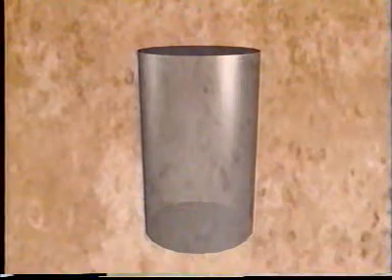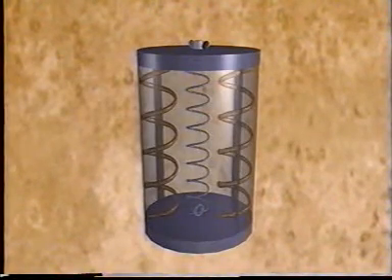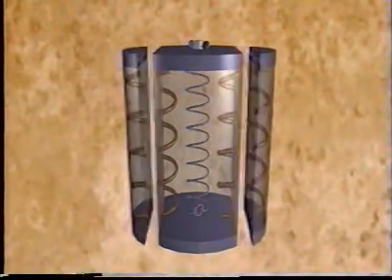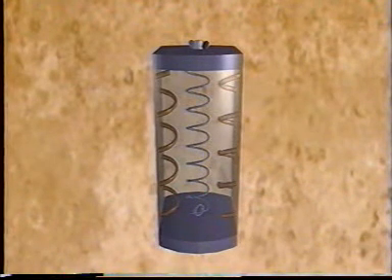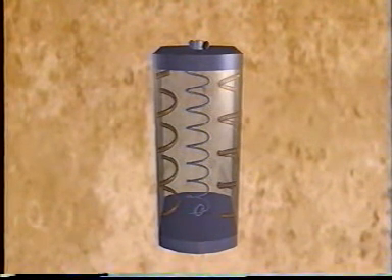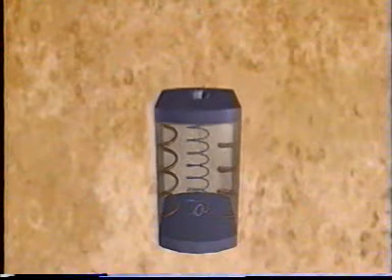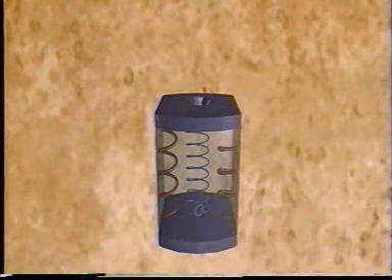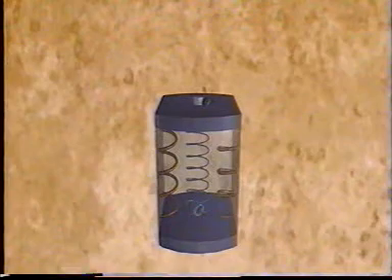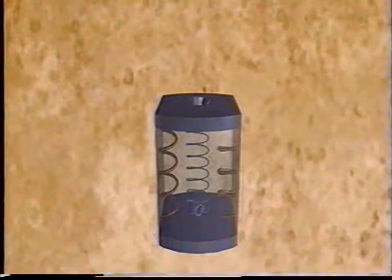Suppose we take a similar bar with the same stress system. We machine the exterior to a considerable depth from the surface. With machining, the external compressive stress will be relieved, permitting the internal tensile stress to relax toward its free length. Relaxing the tensile stress permits the bar to become shorter.